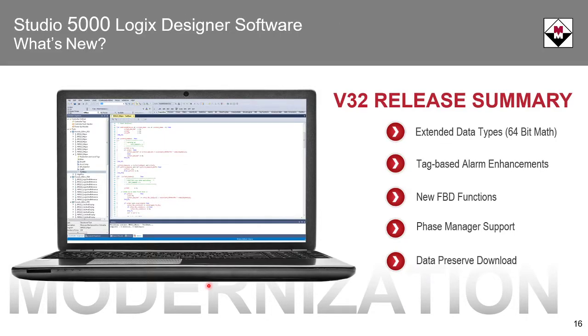They added Logix tag-based alarming, and they added safety instructions for the Kinetix 5700 drives. Version 32 has been out since 2019. Again, I'll be focusing on the key enhancements made to the software in future slides, but for now, here's a summary. With version 32, you get extended 64-bit data types. There's been some tag-based alarm enhancements, new function block functions, phase manager support, and data preserve download capability.